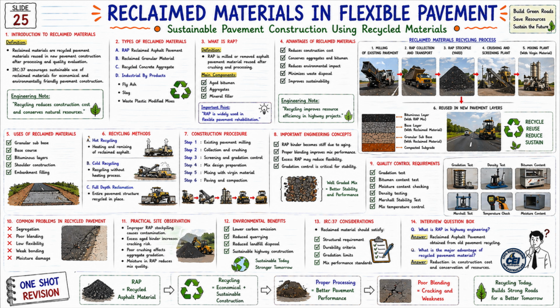Now let us look at the 10th topic. Common problems in recycled pavement. Segregation. Poor blending. Low flexibility. Weak bonding. Moisture damage. And these failures develop due to improper RAP processing.